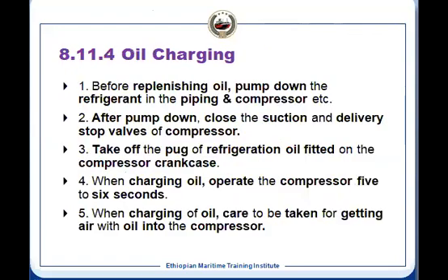So now another thing is oil charging. We need to charge the oil. So in oil charging, how you do the charging. In this case, once you replenish the oil, you need to do the pump down of the refrigerant. So after pumping down, you close the suction and the delivery valve of the compressor. And then you can take out the oil fill plug. There will be an oil fill plug in the compressor crankcase, and there will be a charging procedure.